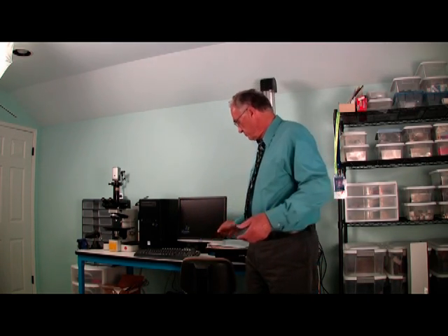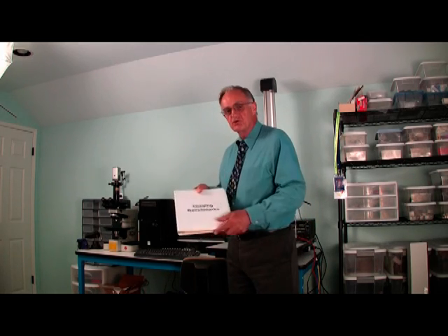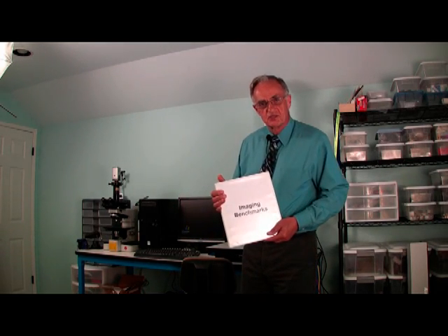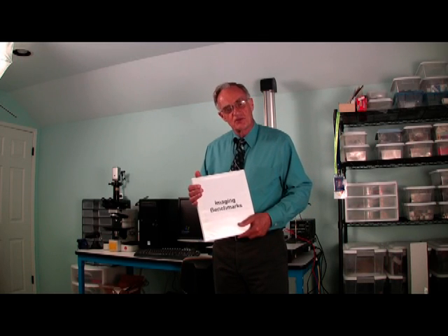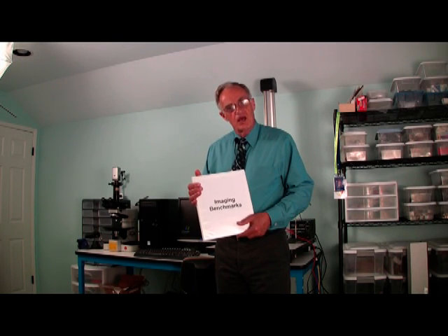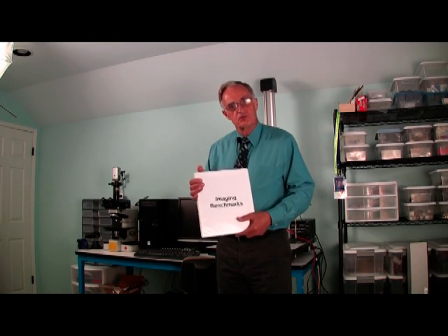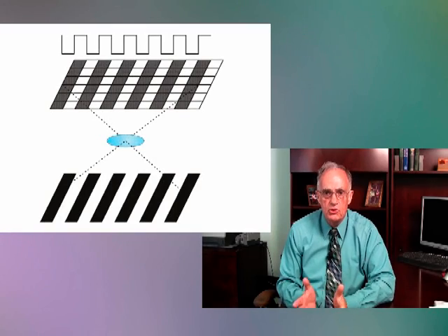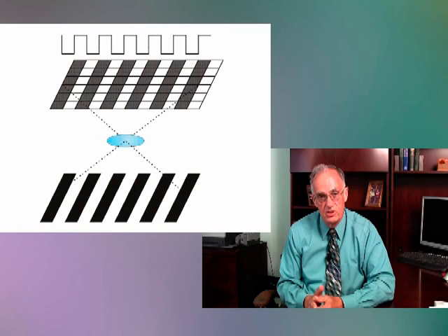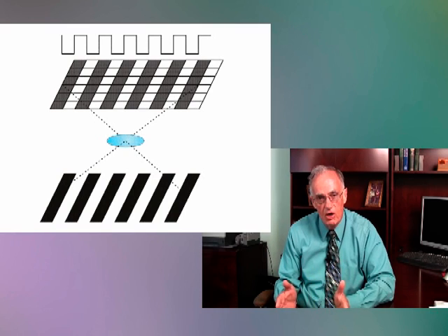When you finish the benchmark, be sure that you record it in your notes. And keep a copy of the images, both on DVD and on a hard printout, which you can put in with your other notes. Now, you should already know the spatial resolution of your vision system. The spatial resolution is the spacing of pixels on your object.